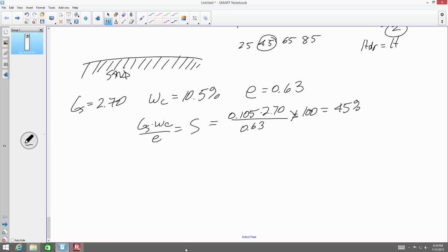Which of the following is true of a normally consolidated clay? It will not settle further under the present loading condition. It appears to have been subject to previous desiccation or drying. It will settle an additional amount if the water table rises. It appears to have been subject to a greater loading condition. I got them all. You might as well pick the other one that's not been picked. One of you will be right.